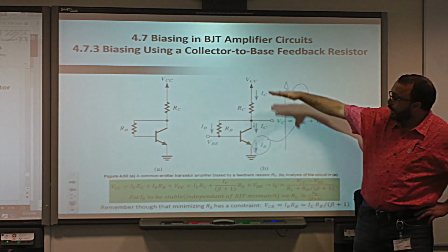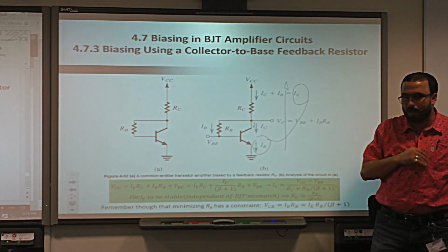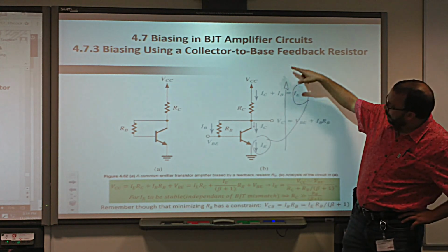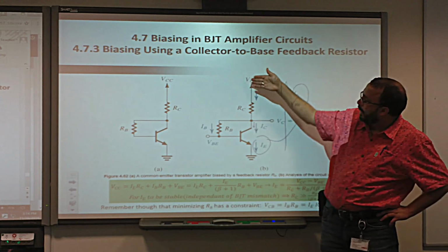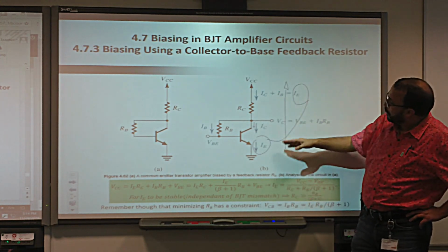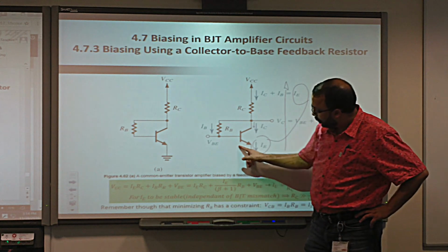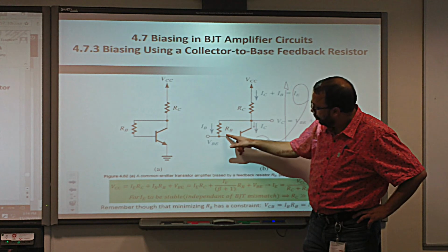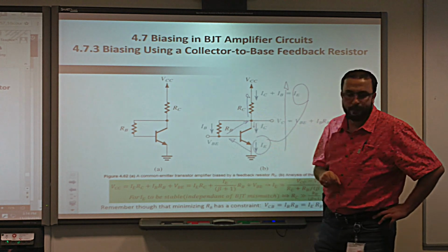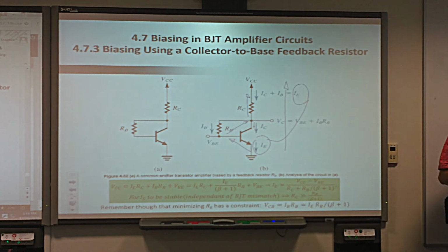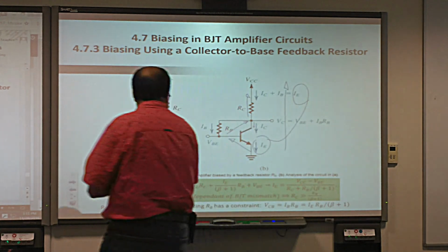Okay? So what comes in is actually IC plus IB, and the same current needs to go up. This is number one. Now, the voltage in here from the ground to VCC, because I need a reference, the only voltage I can really count on is VCC. So this whole voltage is equal to what? I start from the ground. It's going to be equal to this voltage plus this voltage plus this voltage. Yes or no? Clear? Yes. Good? Very good.